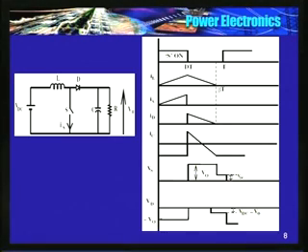So the capacitor is charging only for a shorter duration here, and for the entire remaining period the capacitor is discharging. It is a constant current here, here it is assumed to be linear. So that is the difference. I am just using Kirchhoff's current law to plot the current waveform, that is all.